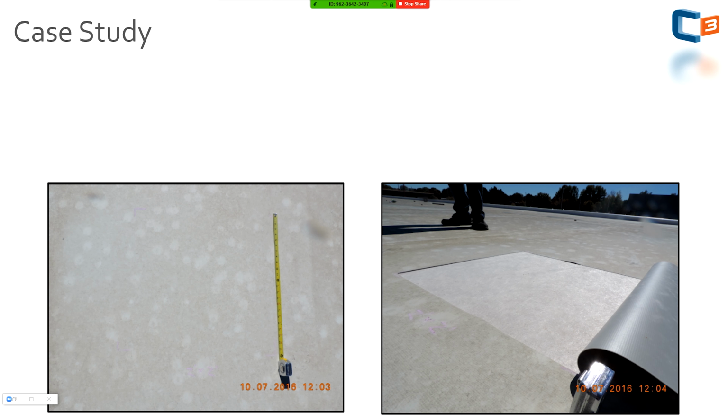damage the roof surface. But in this case, the spatter was so big, and we felt just slight depressions in the substrate of this TPO membrane. We pulled that back, and you can see the facer's intact, the gypsum core is not exposed. So I'm just showing you examples of sometimes when weather data might suggest, like if you had a radar return, say, oh, this is 2-inch hail, it doesn't really tell you the hardness of the hail. That really concludes with on-site collateral indicators.